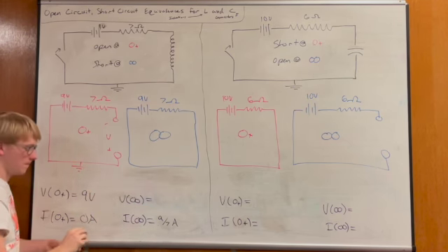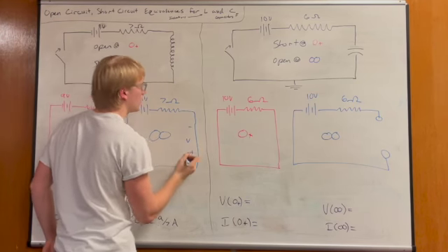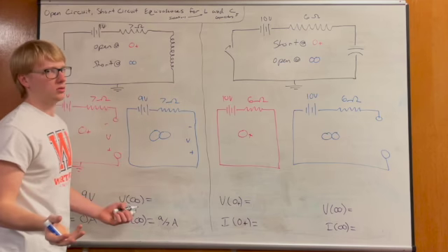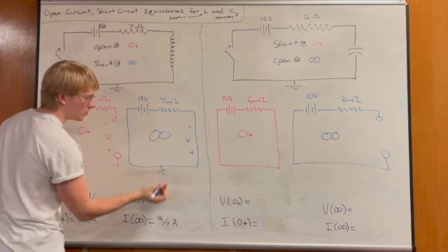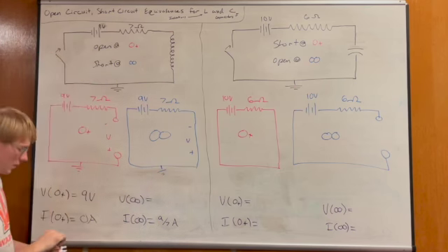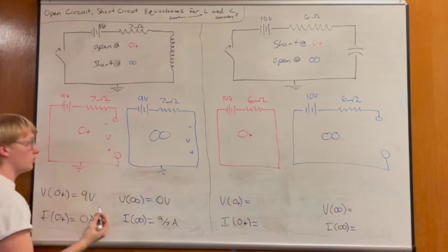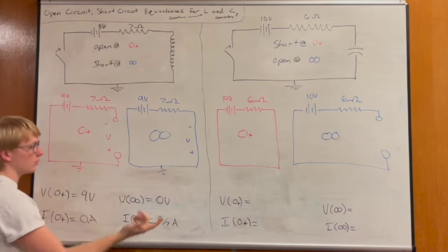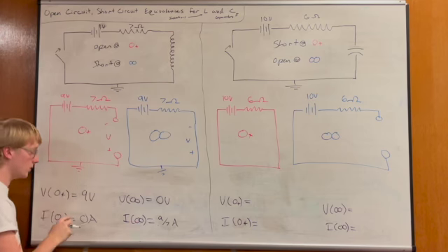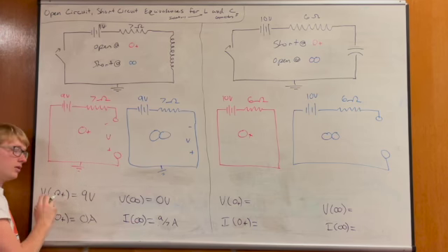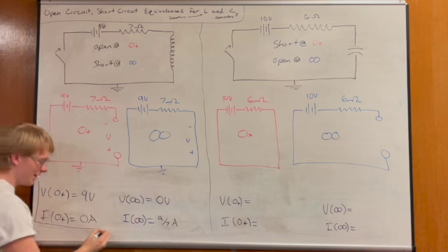And after a long period of time, this jump right here, an inductor, is the same node. So it's going to have the same voltage throughout all of it, whatever we want it to be. It's the ground. And so the voltage jump for that branch is 0. In this particular problem, all we're looking for is initial and final voltages and currents.